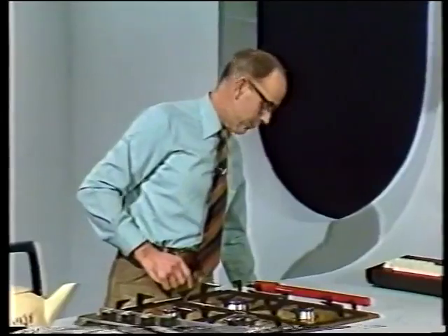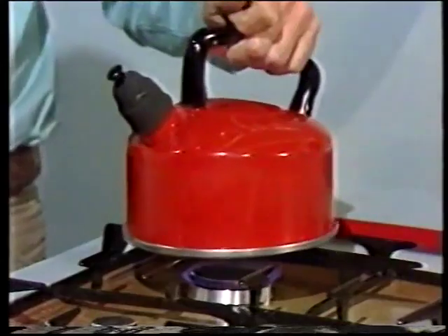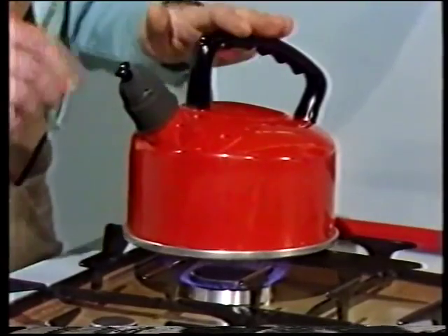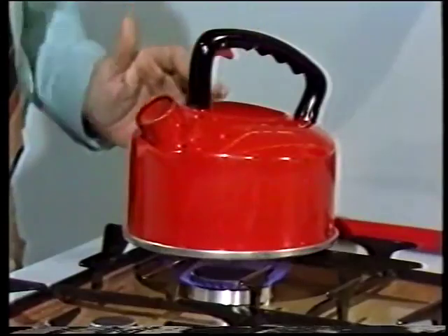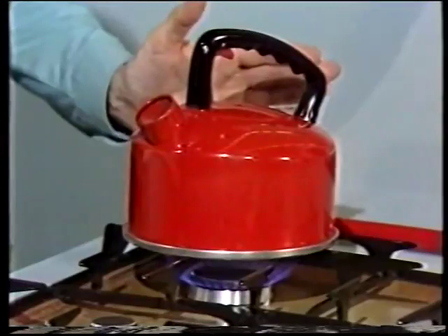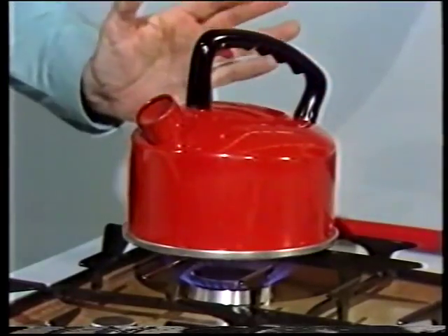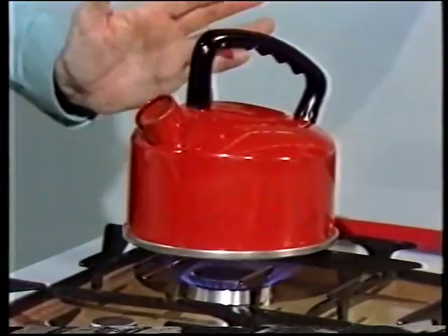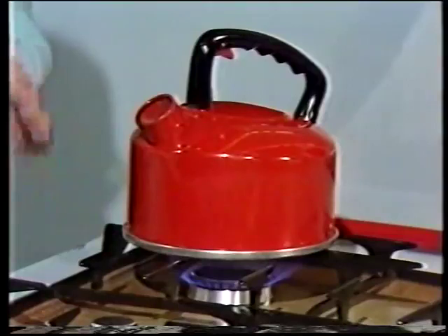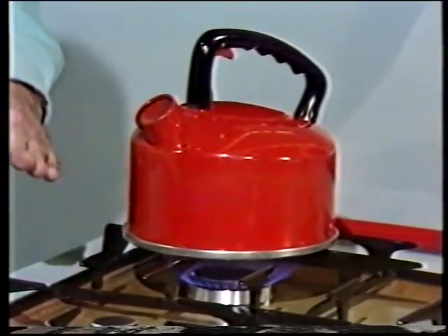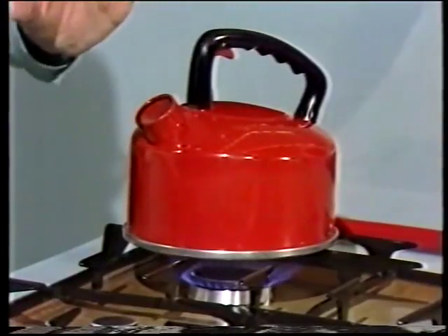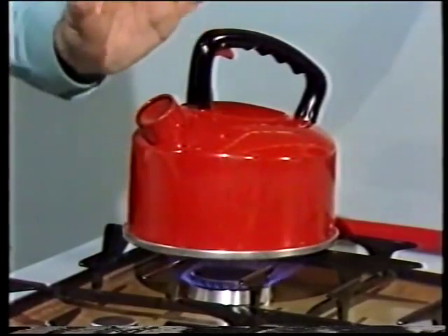But what about this? If I choose to define the system boundary as lying around the external surface of the kettle, the kettle itself now forms part of the system. The energy input to this system is thermal energy, transferred from the hot gas flame across the boundary, here the base of the kettle. The energy output from the system is thermal energy, mostly as steam from the spout, but also that lost from the surface of the kettle itself.